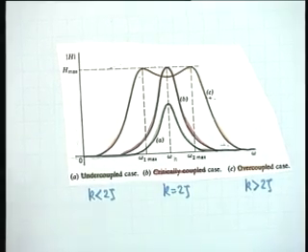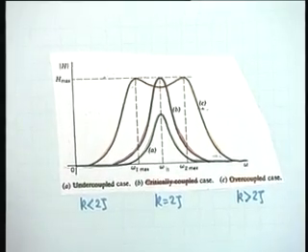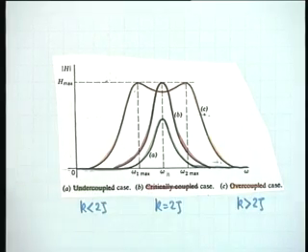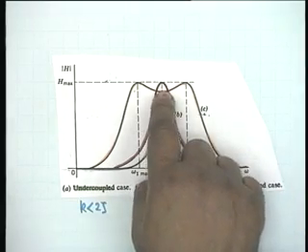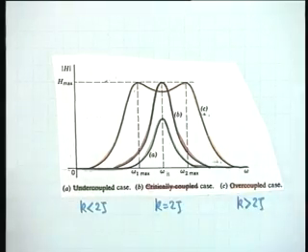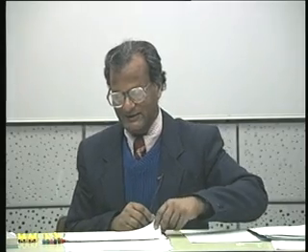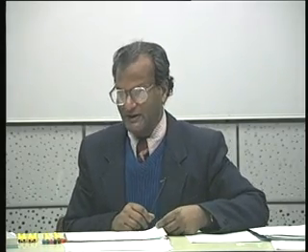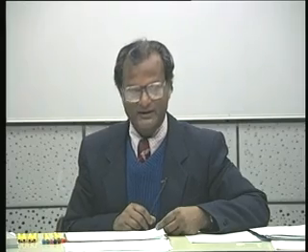Is it possible to have 3 half power points at a point exactly where it is 1 by root 2? Very good. Yes, it is possible. If the dip is exactly 1 by root 2 times the maximum, there are 3 half power points. Yes. That is correct. But in every case, well, usually one does not want that.